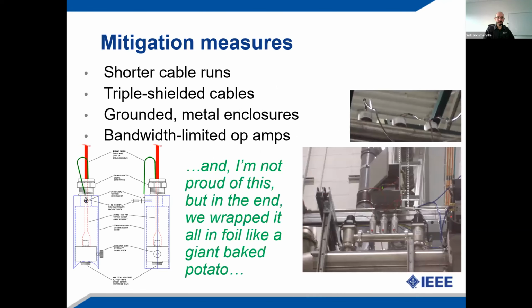And so we had to up our shielding game. This is a story about shielding. So we have some nice metal cans that we put over our oxygen sensor. We have triple shielded cables. We have shorter cable runs, grounded everything as well as we can.